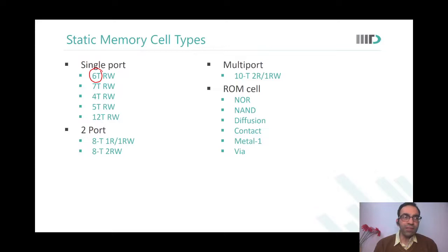Similarly, suppose we're talking about a set-top box and we say that there are 4 customers that a particular company, say Broadcom, has to handle. 4 customers could be Airtel, Jio, Dish TV, and so on. Each one of them needs different programming for their boot code because they have different validation codes with their satellites. So you need to put a ROM in those chips and you need to program it according to the vendor.